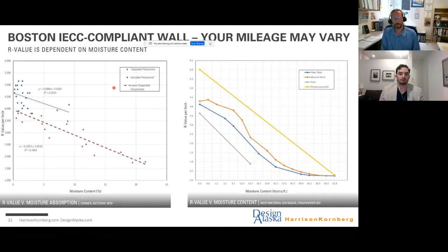And so I just want to pause here and say, now that we've discussed the moisture damage, this isn't all about indoor air quality or life safety. Even the most hawkish among us on energy stuff, which is great, we all need to be very aggressive in our energy efficiency, but we need to realize that if we are ignoring the moisture performance of the wall assembly, we're shooting ourselves in the foot on the thermal side, because wet insulation is bad insulation.